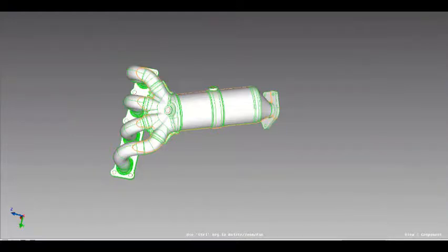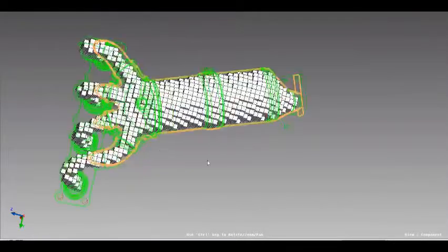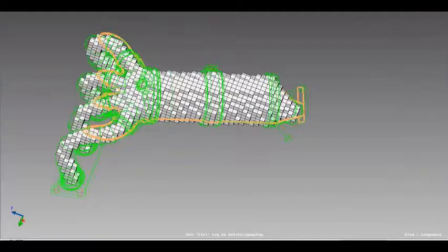Once the user clicks on find inner cavity, MeshWorks automatically detects the inner cavity, and it will create hexa elements inside that, which will be the input to the next step. Once the inner cavity has been generated, a user has to select the generated FE and just say isolate. Once the user clicks on isolate, MeshWorks will try to find the tolerance between the inner surfaces and the cavity that was generated, and it will organize all the inner surfaces into different PIDs, which makes the wet surface.